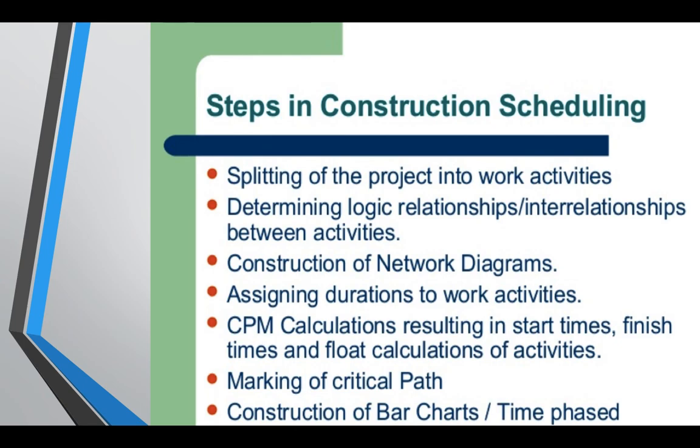So steps in construction scheduling. What's the first step? The first step is splitting the project into work activities. Then you determine the logic relationship, the interrelationship between activities. Does it make sense to have this activity start after that activity? What activities can I have go together? Do I need to have that activity complete before I can start the next one? So that's what you're going to be doing.